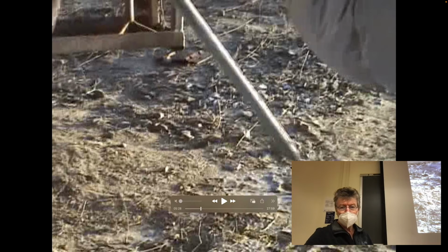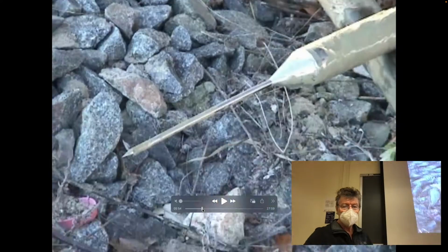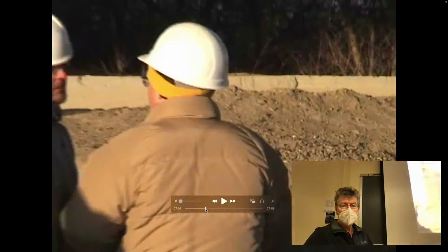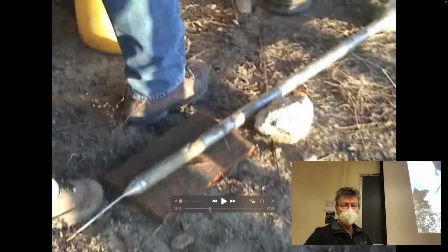So you lose it. So you can see here that there's something a bit longer than a pencil, probably thinner than a pencil, and right at the tip it has a pressure transducer. So the idea is you could push this down the hole, at least get beyond the edge of the hole by this amount, the length of the pencil, to be able to get a pristine measurement of the pressure that you had. And so it's more of a scientific project to be able to evaluate that rather than a straight site investigation. There you go. It bent. It's not very durable. And ultimately it was deployed 2,000 feet into the Gulf of Mexico. And so this was just a drilling rig that was used to be able to sample that.